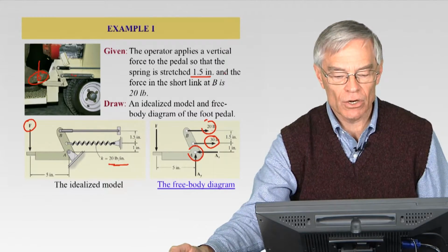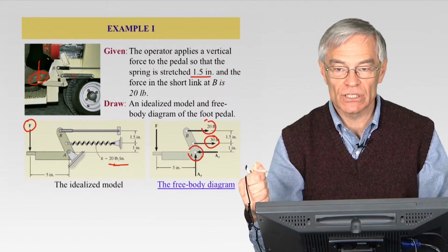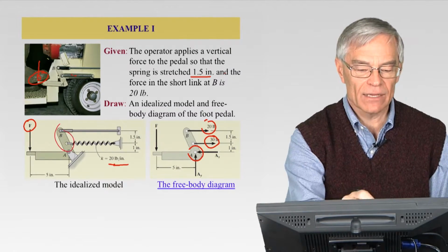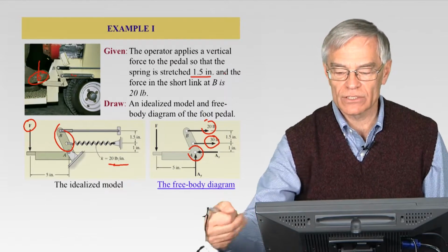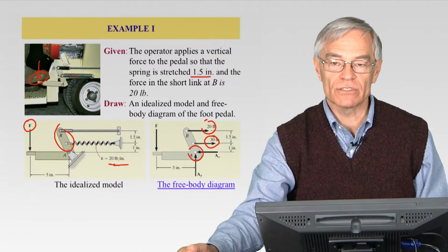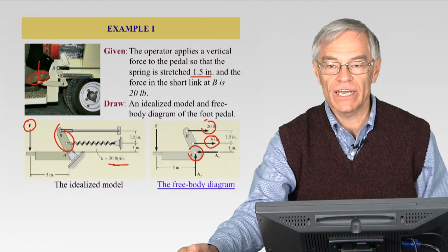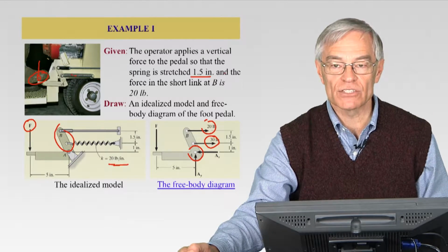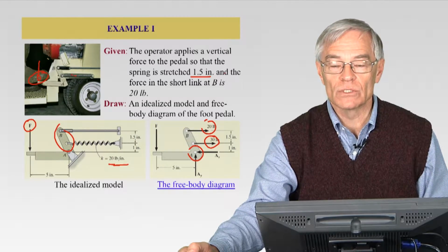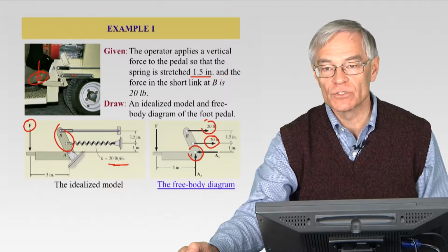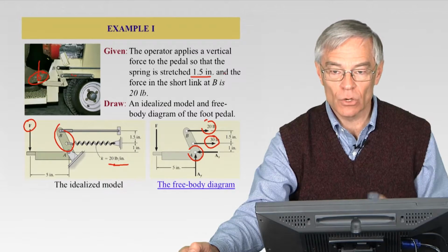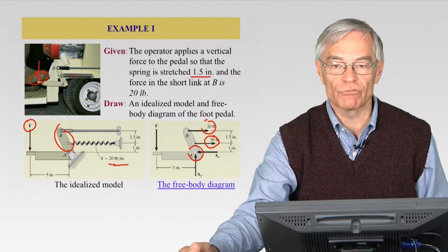And again, because we are stretching the spring, basically that force in the spring is trying to pull that pin, this link back, so we get the 20 pounds directed to the right. Don't worry about trying to pick the right direction if you didn't learn this in statics. There's only one case where it's essential that you get the right direction, and that's friction. For the most part, we're not going to be worried about friction in our project, so you can guess the best you can in terms of direction, but the mathematics will work it out and show you the right direction. The only time that's not true, as I said, is with the friction force.